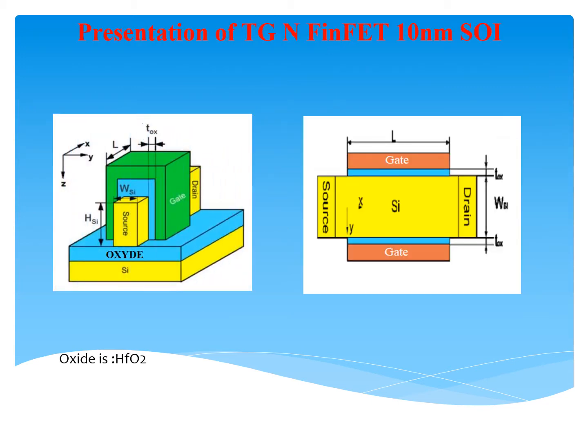Now, presentation of Tri-Gate FinFET 10 nanometer SOI. The left figure presents the structure of the device, where HSE is the height of the fin, WSE is the width of the fin, and L is the channel length.